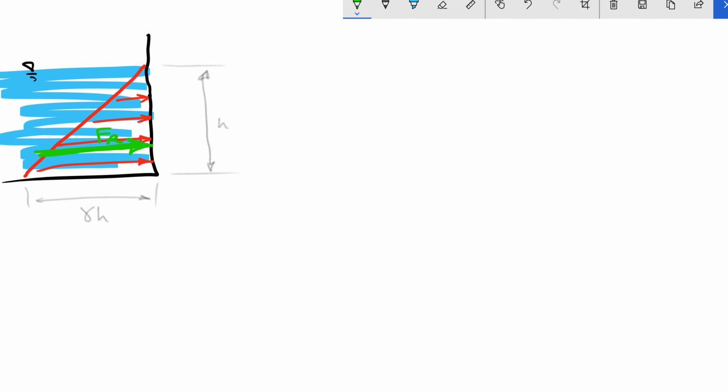Okay, let's see. I want to find the magnitude of the resultant force. I know the formula was gamma h A, but h is hC. So let me check. This part is like the pressure at the centroid multiplied by area, which is good, and it is going to be gamma, the centroid is h divided by 2, times area. Beautiful. So I found the magnitude.